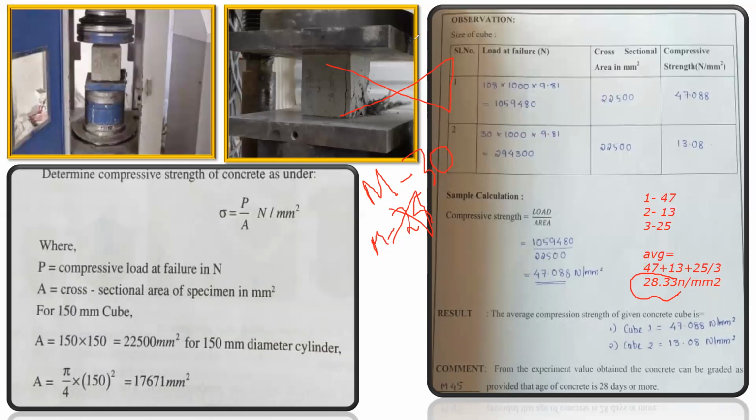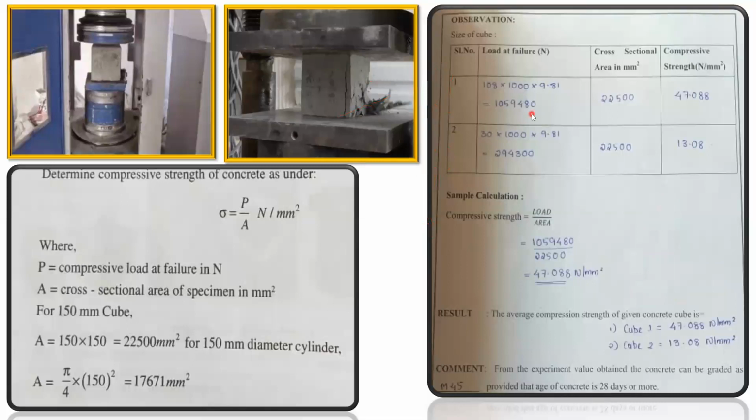Yeah, right. So this was the entire procedure of compressive strength testing on the concrete. And one more point: whenever you apply the load, the final value should not deviate by 10 or 15% of the mean value. That means, because these are practical things, simply doing the cube testing will not help us.